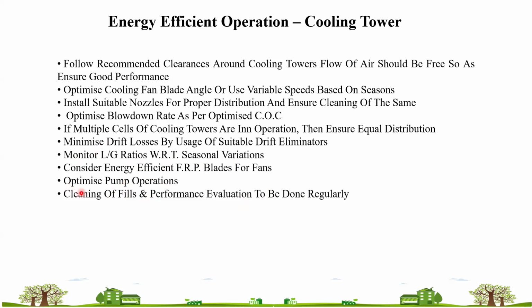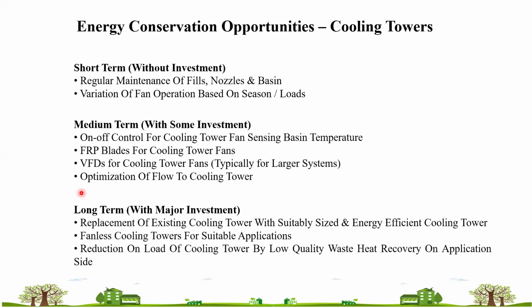Fill cleaning is the primary activity and has to be done quarterly or once in 6 months. If your fills are majorly choked or broken, you need to replace them. So that's how preventive maintenance has to be done in a cooling tower.